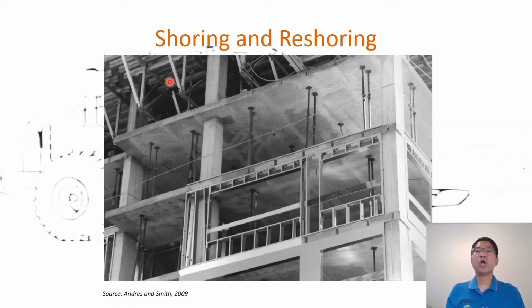But it's not economical to leave the table form here for 28 days until it gets strength. You would need a lot of material, a lot of formwork set up, to wait for 28 days to remove.